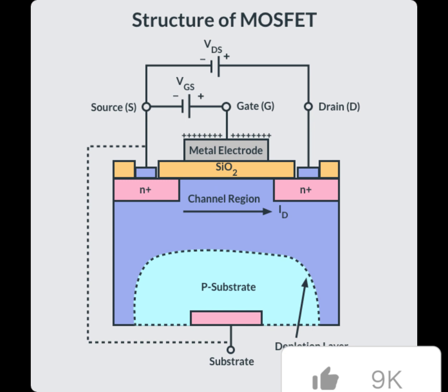So why MOSFETs over BJTs? MOSFETs are particularly useful in amplifiers due to their input impedance being nearly infinite, which allows the amplifier to capture almost all of the incoming signal. The main advantage is that it requires almost no input current to control the load current, and that's why we choose MOSFETs over BJTs.